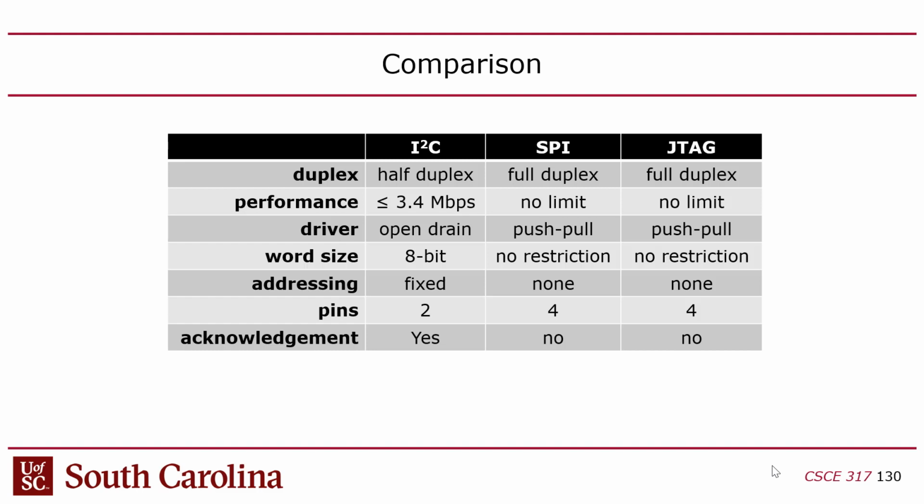So now you have to be careful, because depending on how you wrote your code, you may have constraints on those two parameters. For example, your code may force you to have a dim period that is at least 200 times that of the PWM period, right? Depending on how you wrote the code, you may have restrictions on how you can set those parameters. So we'll ask you, the idea is just to make sure you understand what the implications of that are.